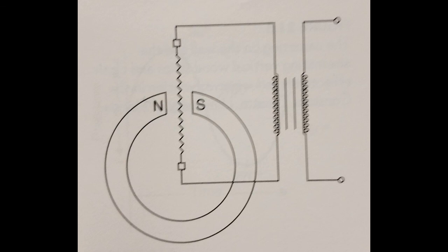Here, we're going to start discussing the differences in microphones. There are three basic types of microphones used in theatrical sound design. The ribbon microphone. Ribbon microphones use an extremely thin strip of corrugated metal suspended between two poles of a magnet. The air pressure of the sound waves moves the metal back and forth to generate an induced voltage between the two ends of the ribbon. That voltage mimics the frequency and intensity of the sound source.